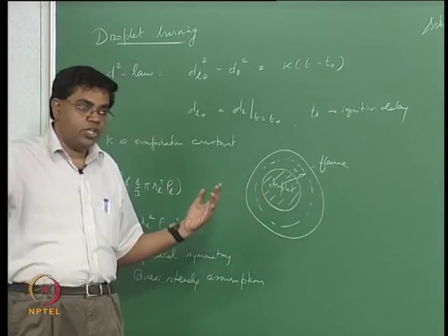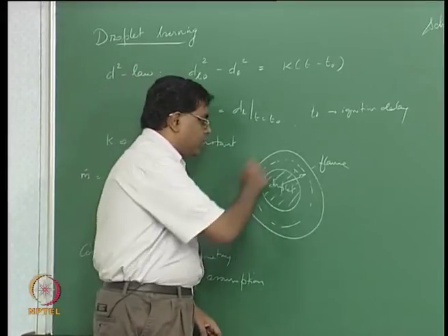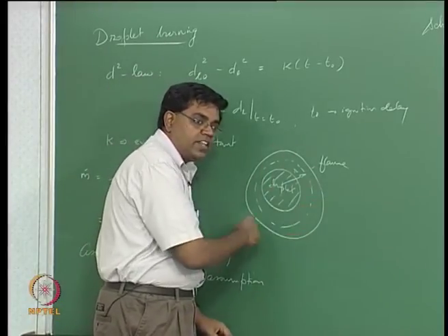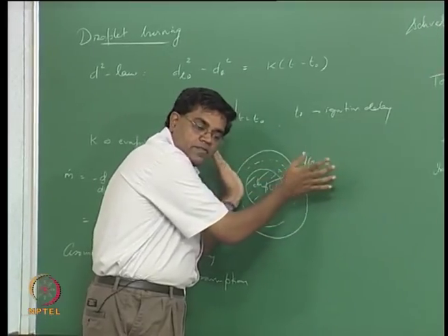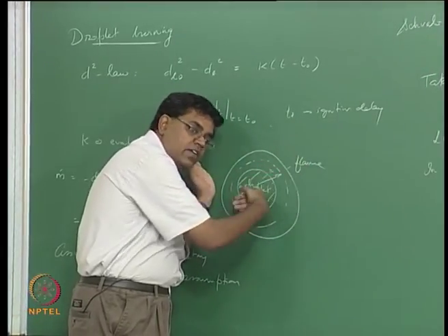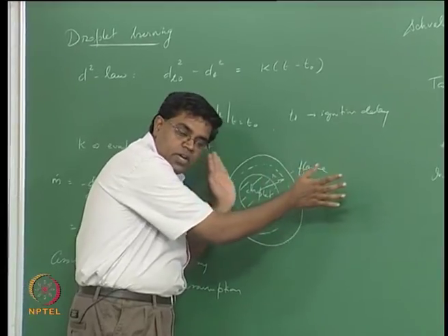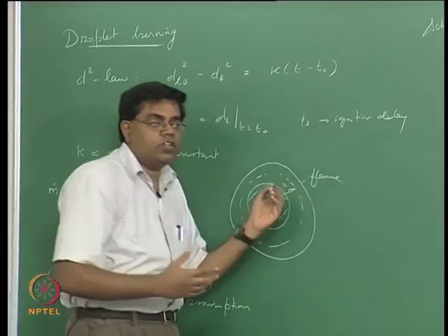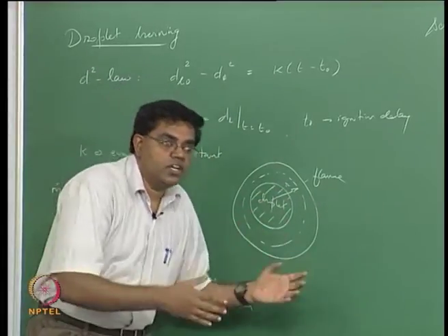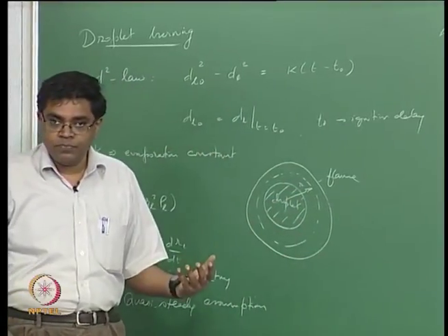vaporization temperature of Al2O3. So you form aluminum oxide vapor at the flame, which now tries to diffuse out from the flame radially inward and radially outward, and a little bit further out the temperatures are now low enough for the Al2O3 vapor to condense into Al2O3 liquid.